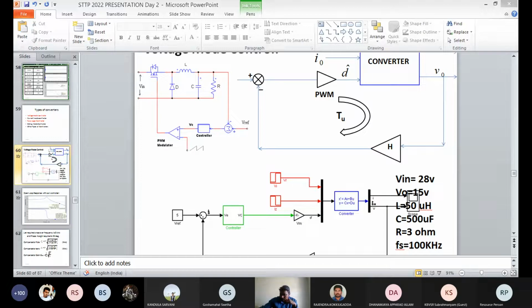Even though you are getting the time response as you decided, the closed loop system may be unstable by design after designing the controller by the trial and error approach like this. That means a simple PI control is nothing but taking the KP and taking the integral with KI, and directly connecting them with the help of the summer. This is the simple PI controller. Actually it is not a correct method.